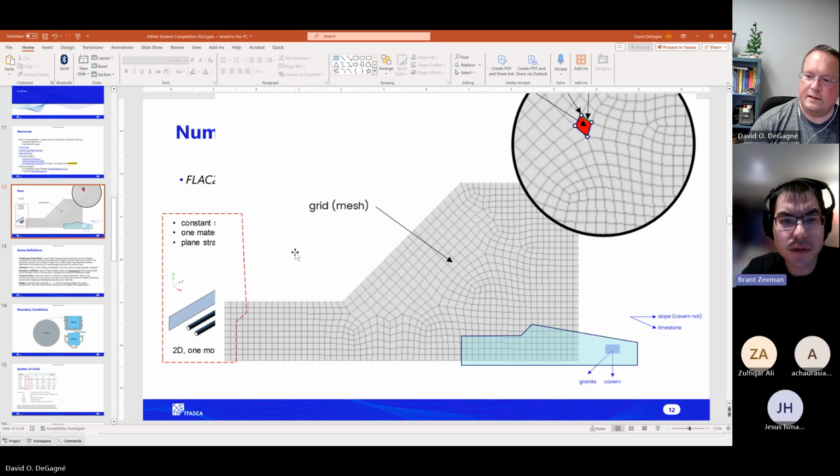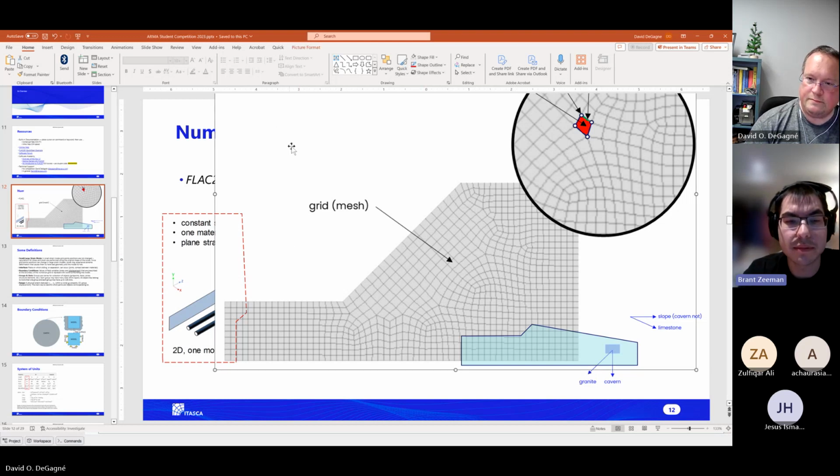Okay. So how much control do you have over the mesh? Can you do, say, variable cell sizes if you wanted more detail around a certain area or a certain interface? Yeah, completely. You'd have to set that up. So for example, say there was a tunnel here, a circular tunnel. When you create the outlines of the model, you'd probably want to put a little box around it.